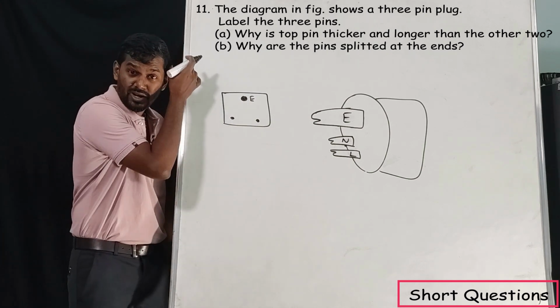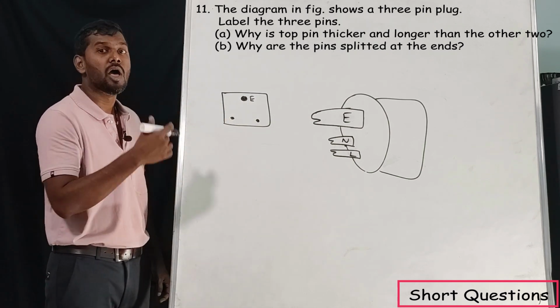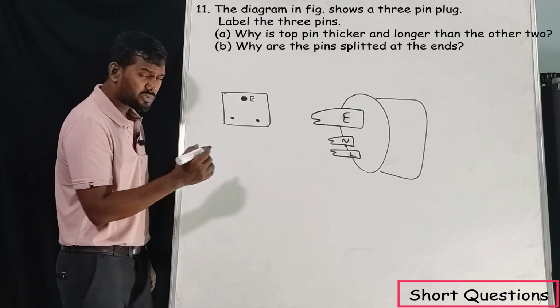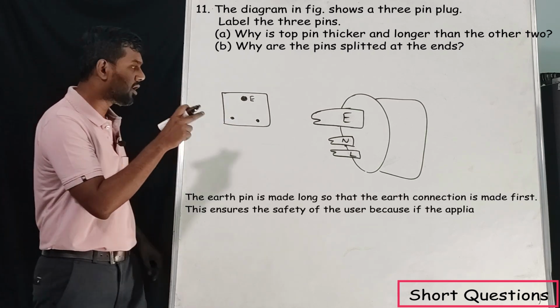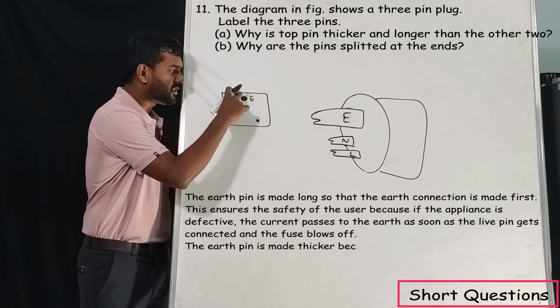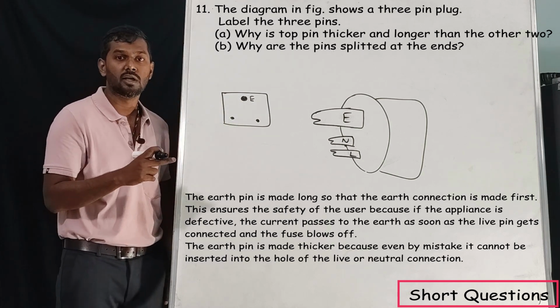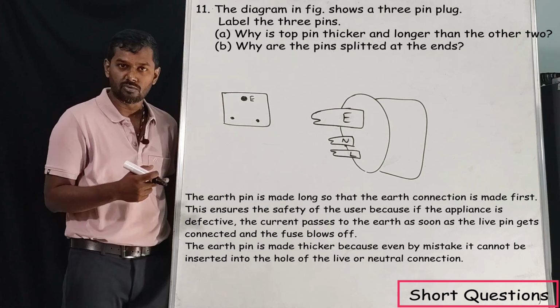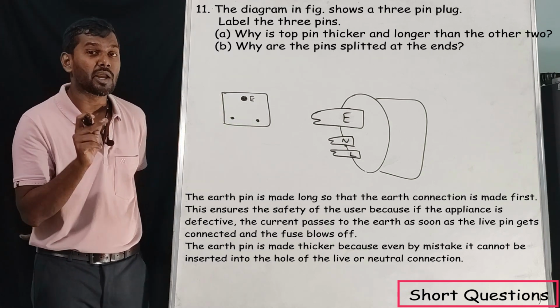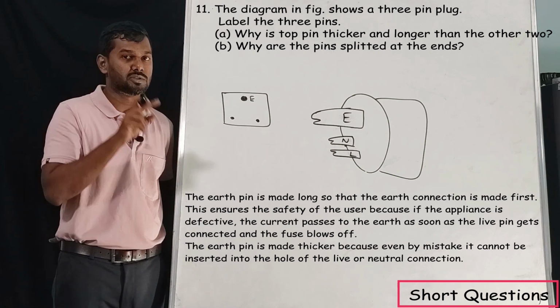Now why is it made longer? See, the first thing is, whenever it is long, what happens? It is going to get the first connection. So when it gets the earthing connection first, it is going to ensure the safety of the user.